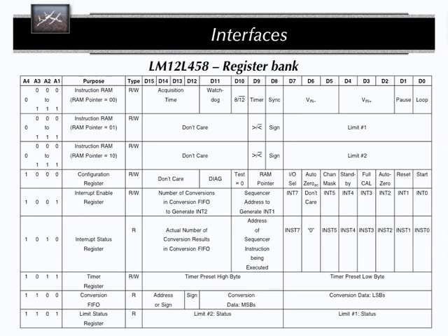Okay, welcome to address lines. We see a few of the address lines here now enumerated, which means inside this global memory block, which we allocate for our AD converter device, we have things happening at different addresses inside this block. These addresses are just enumerated here. What happens inside of them? Now we assume a 16-bit bus. Hope we have a 16-bit bus to connect to. Then you see what every single bit in these words, which you see in memory, is actually doing or indicating.